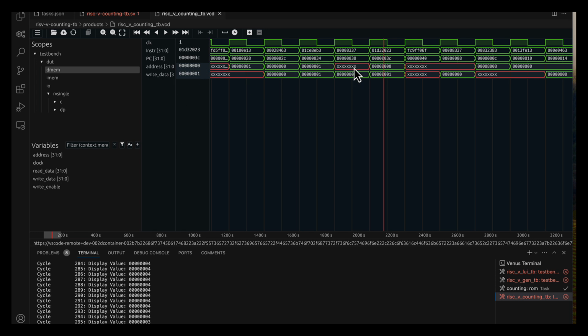Okay, so that's really useful, particularly if our instructions aren't behaving the way we want them to. We can actually use this as a means of debugging. In particular, if we get something where everything starts going to uninitialized values, we can use these traces and kind of work backwards, try and figure out what the last valid instruction was. And if we want to, we can even dig down and look at all of the different control signals.